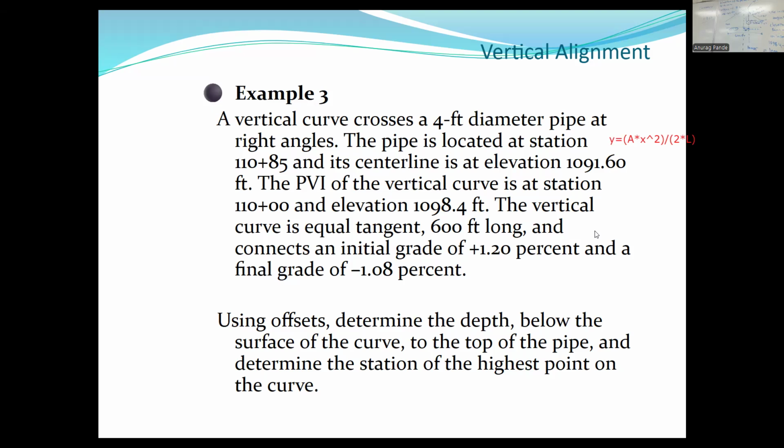So anytime you're talking about estimating these clearances, which is a lot of times in roadway design, the offset equation can provide an alternative way. Again, you have to be careful about what distances you're calculating, but it can make your calculation life a little bit easier rather than estimating the 3 parameters of the vertical curve equation and so on and so forth. But ultimately, you're looking for the elevation of this point. You could have gotten it by other means, but the calculation on these were much simpler in terms of just making sure that we are aware of that approach.